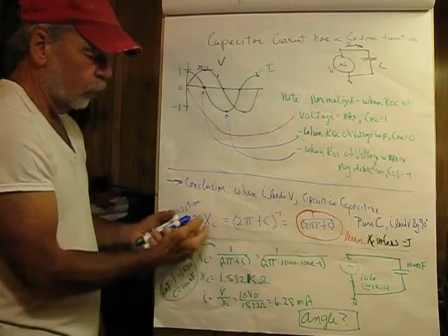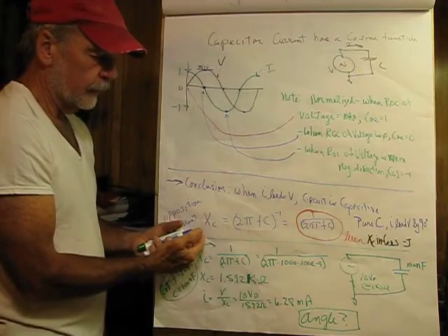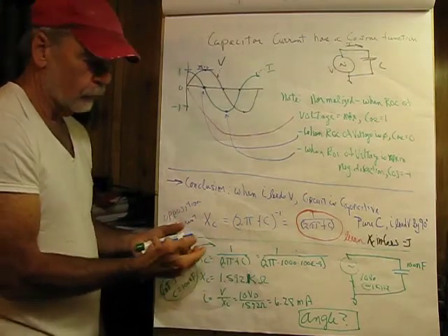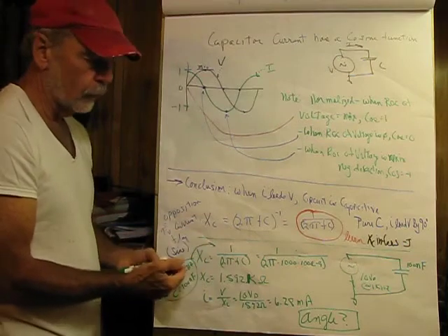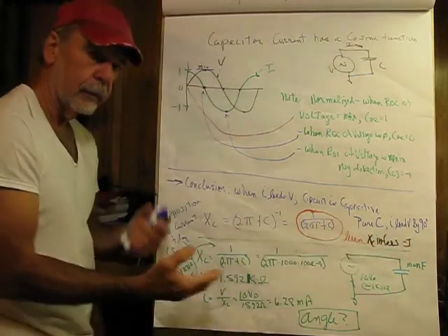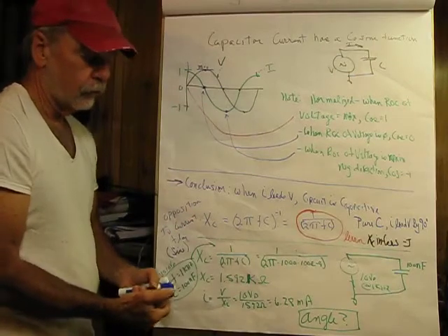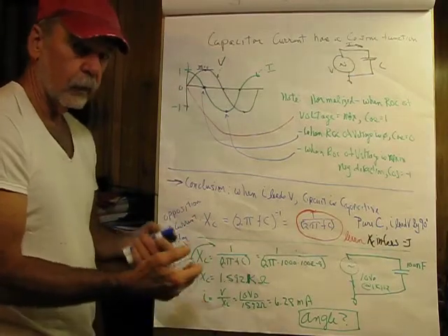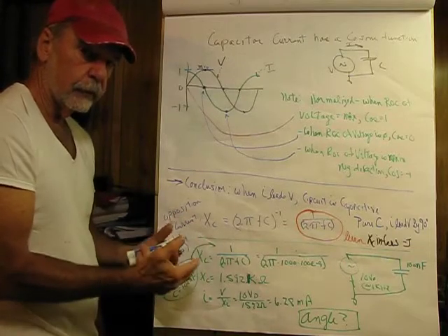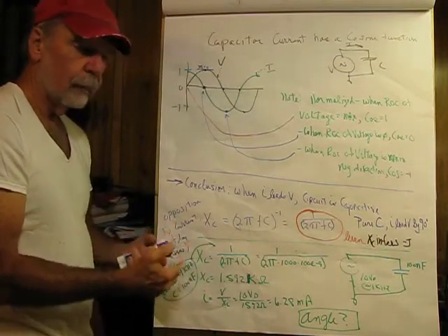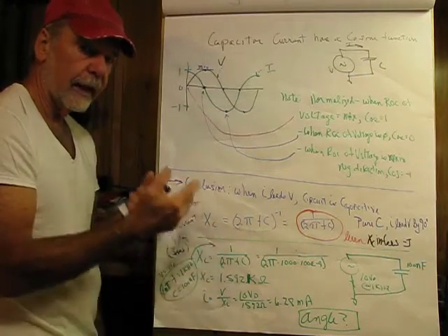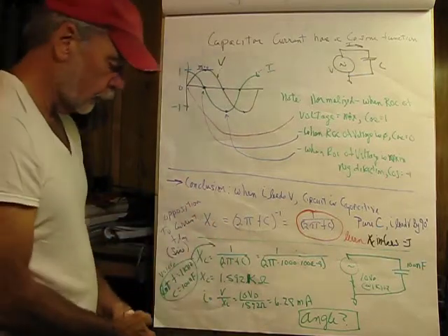So when I say the word capacitive reactance, and remembering that we have phasors and so forth, imaginary components, it implies -J. It's built into the word. Just like signal loss equals a gain in -dB, is built into the word loss. Ripple rejection ratio has a negative built into it. It automatically infers a loss.